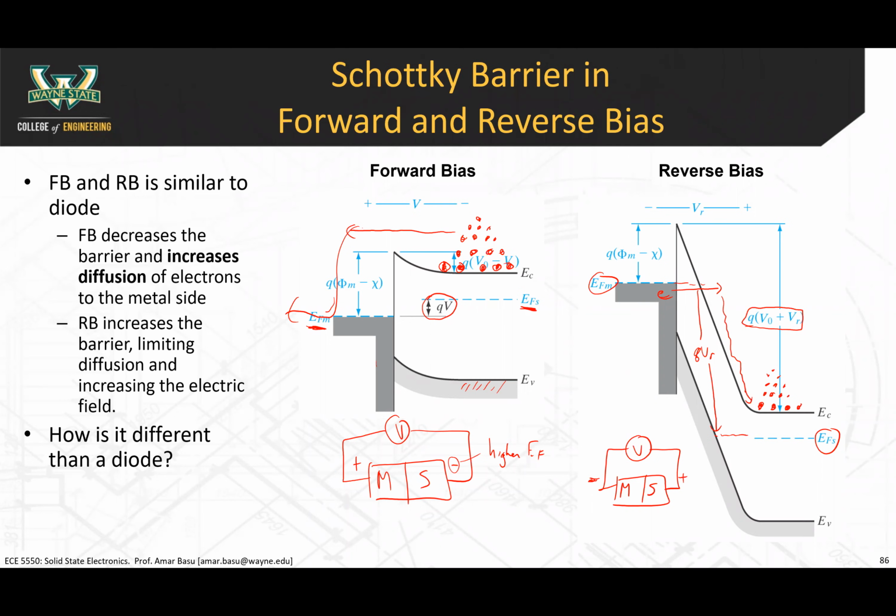Just by applying a voltage. So just by applying a voltage, this electron here could go across in energy like this. By applying a voltage, what you're doing is you're changing the Fermi levels on the two sides. Only by adding energy to the system through optical stimulation, for example, could you get an electron to go to a higher energy state, to go up like this and possibly be ionized. But in this case, what's happening is you're changing the Fermi level on this side.